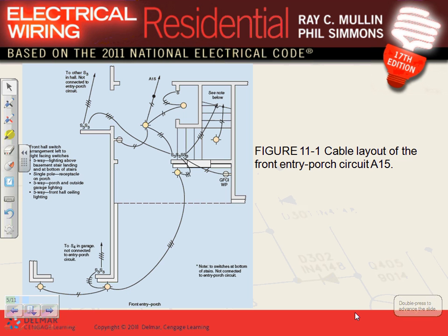All right, so I'm going to go directly, guys, my friends, into this circuit. Here's my circuit right here. They brought the circuit, Chris, into the light, no problem. From the light, as you can see, what they did, they stole a receptacle. So the word lighting circuit implies also general purpose receptacles. So what they did, they took the circuit here, they put the receptacle, hot and neutral, no problem, everybody can see that.